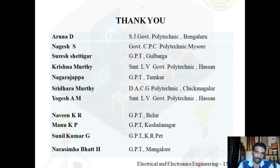So in this particular session, we have seen how the speed of a DC shunt motor can be varied by varying different parameters, that is by varying flux, by varying voltage, and by varying the armature circuit resistance. And also we have seen in detail about the flux control method or the field control method of a DC shunt motor. Thank you.